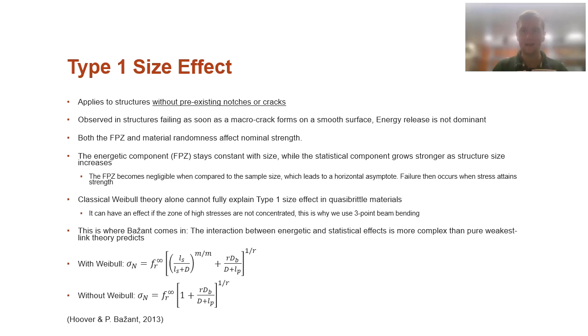It's not related to this buildup of energy at a certain point. So that's why we can come in and say, maybe material randomness does affect the strength. Maybe there is a world where the Weibull theory may explain this. Well, maybe because we're not putting our own notch in there, maybe it is running into some problems with statistical reasoning, that maybe it is finding an area of weak strength. And we kind of see that in these larger components.